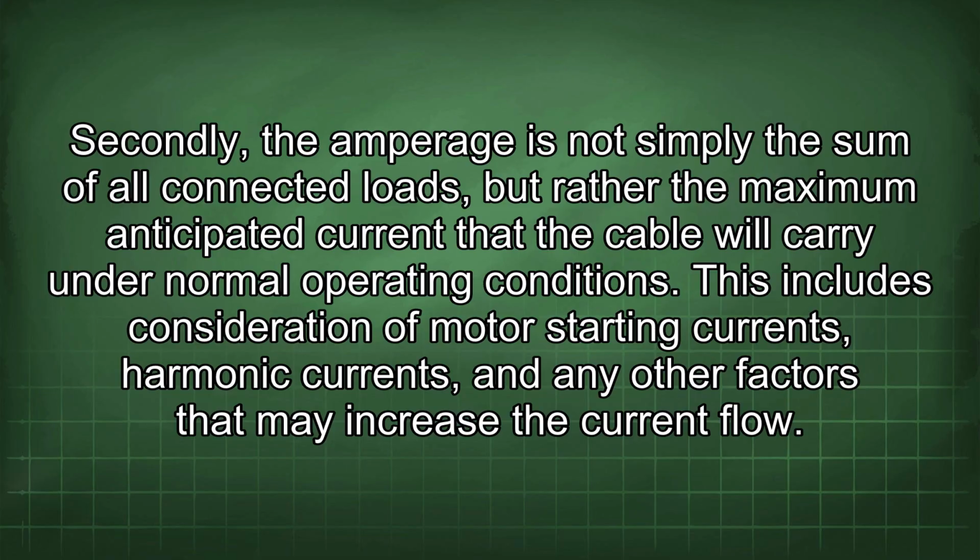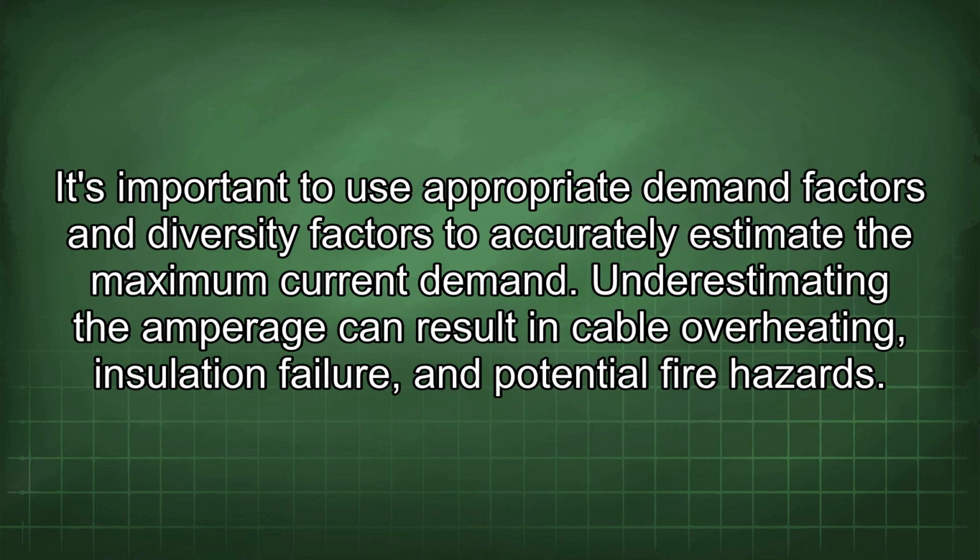This includes consideration of motor starting currents, harmonic currents, and any other factors that may increase the current flow. It's important to use appropriate demand factors and diversity factors to accurately estimate the maximum current demand. Underestimating the amperage can result in cable overheating, insulation failure, and potential fire hazards.